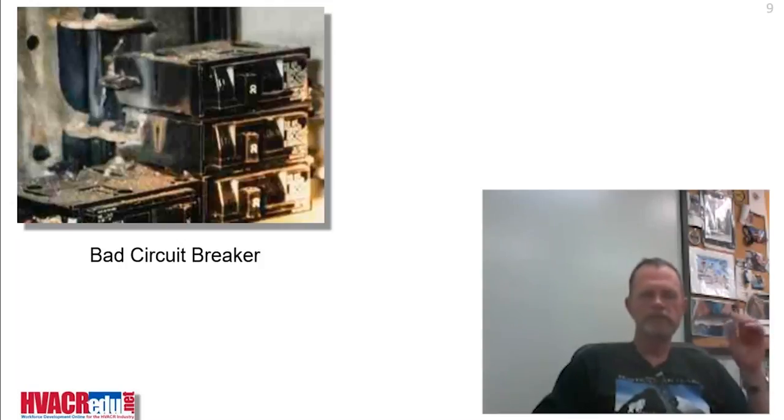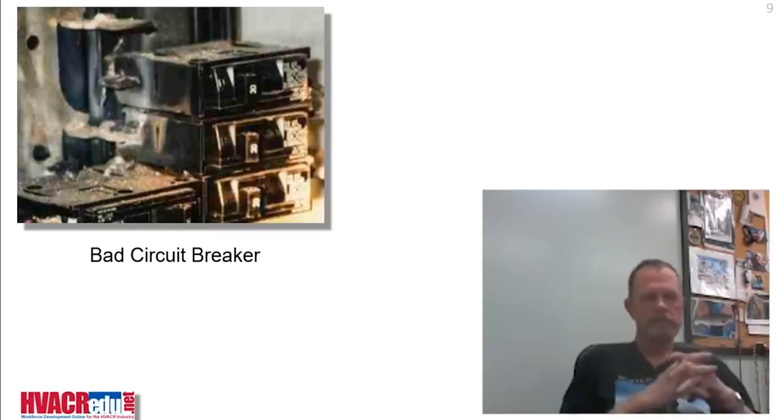So if you have mystery trips or intermittent circuit breaker trips, those kinds of issues happening to you, in all the years that I ran service, and still take care of all my electrical here on the ranch, they happen occasionally. A circuit breaker will start dropping voltage through it, and boom, it's time to change that breaker, because eventually it's going to start doing a nuisance trip thing, etc.